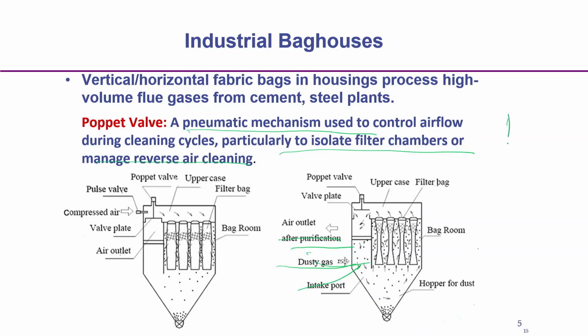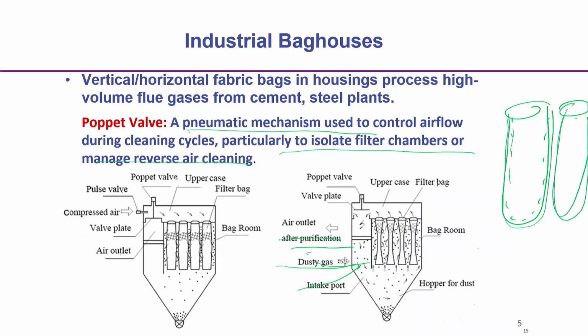Now, the large size bags are there, with frames, and on the frames these bags are hung, the height may be very high. On the metallic frame, the textile bag filters are arranged. Now, here the dusty air is coming and it is penetrating through the bags from the outer surface, and the dust particles are arrested at the surface.